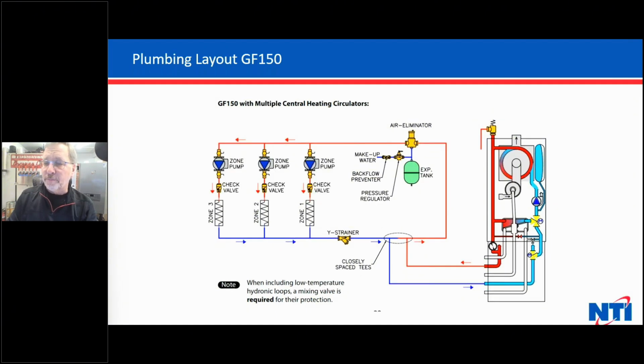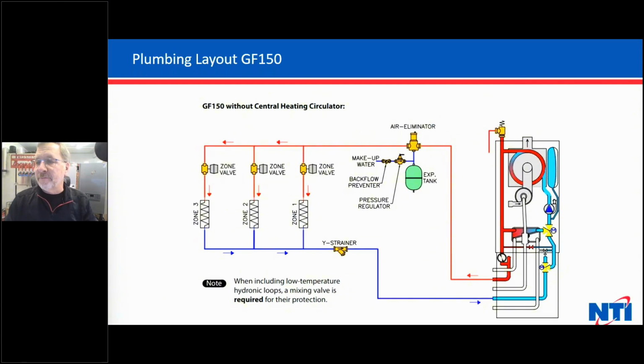Though, please note, you'll see when I'm doing this, I put a separate expansion tank on the heating system. And I have to, because this built-in tank is only sized for the coil and the amount of water in the coil in the air handler and the coil in the heat exchanger. So that's all that expansion tank is good for. So when you put additional zones on there, you do have to put in another expansion tank, another air scoop, and another fill valve.